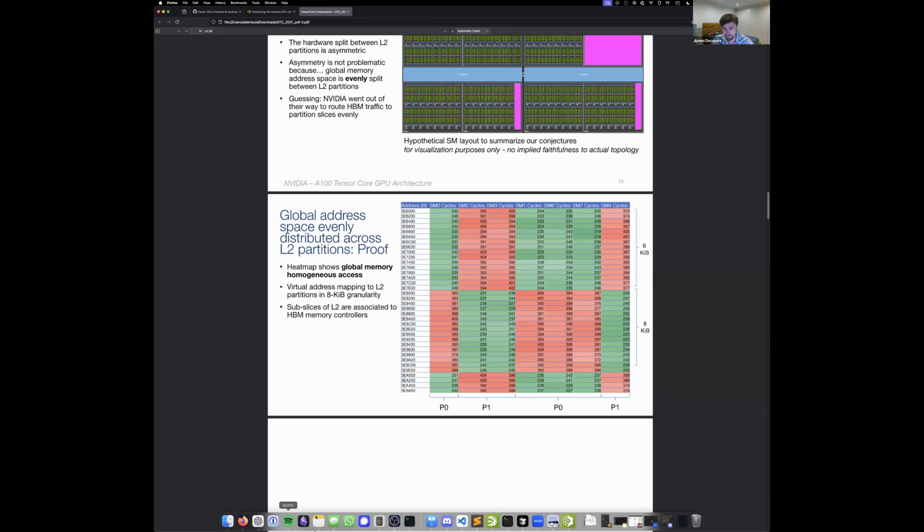But what this gives me on H200 is a 2% performance improvement, which is not amazing, but it's kind of nice for a GELU kernel. For memcpy, it's kind of the same performance. But then it actually reduces power from 490 watts to 435. So it's like an 11% power efficiency improvement, which is actually quite a lot. Like, as we've seen, that's about 20 nuclear reactors.